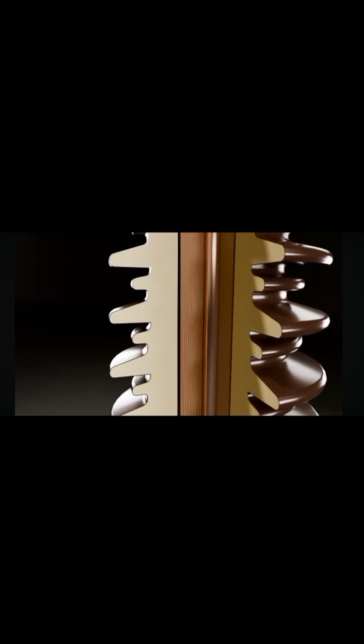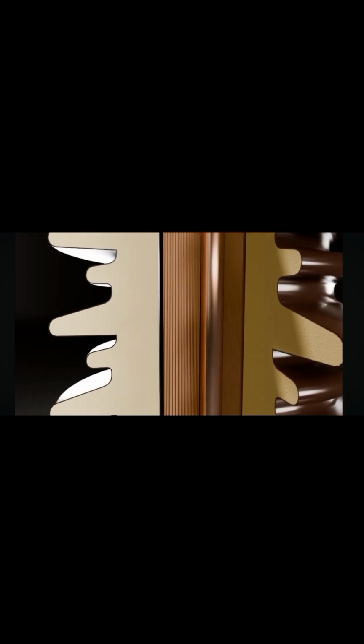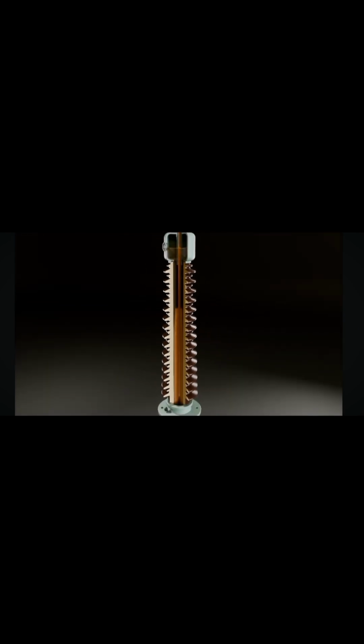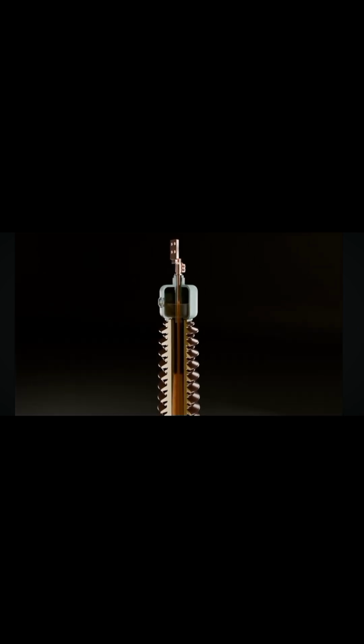This arrangement acts like numerous capacitors connected in series. This configuration ensures a uniform distribution of voltage within the bushing. These types of bushings are filled with insulating mineral oil to further enhance their voltage handling capacity. The top of the bushing includes an oil expansion chamber to accommodate the expansion and contraction of the oil due to temperature changes.